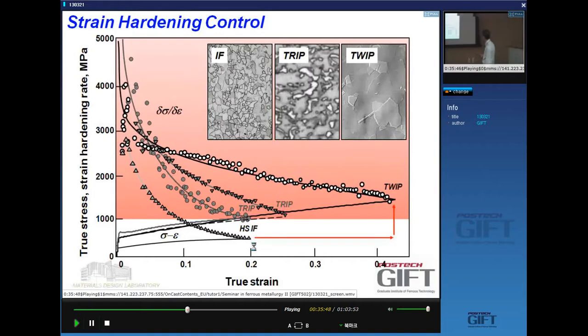In the case of TWIP steels, we have resolutely gone from ferritic alloys to austenitic alloys. And we're in a system with a much lower stacking fault energy. What is interesting is that the TRIP steels, which may not give such a huge improvement, are also pretty interesting, because they achieve these strength levels and these ductility increases at relatively low alloying contents. And this is a route that is gaining popularity. This is one of the reasons why we are seeing these vast and very diffuse clouds of composition where people are trying to see which one is the solution.